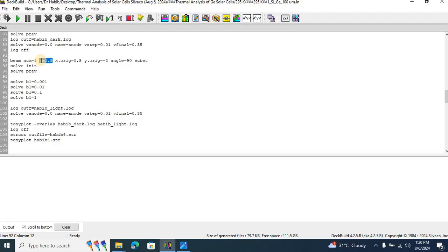There is a difference in spectra measured at the top of the atmosphere and at the surface due to atmospheric scattering and absorption. The path length of light in the atmosphere depends on the angle, which will vary with the time of the day. This is given by the air mass number, which is the secant of the angle between the sun and the zenith, or we can say the vertical axis.